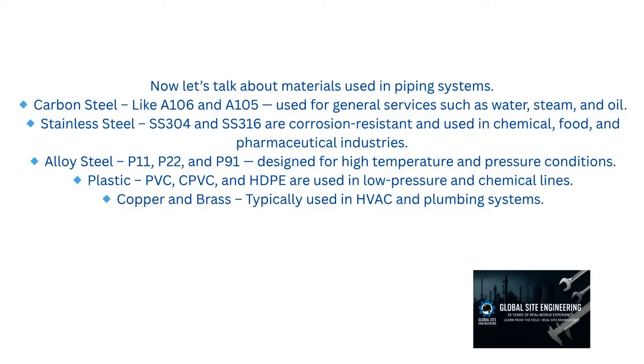Alloy steel, P11, P22, and P91, designed for high temperature and pressure conditions. Plastic, PVC, CPVC, and HDPE are used in low pressure and chemical lines. Copper and brass, typically used in HVAC and plumbing systems.